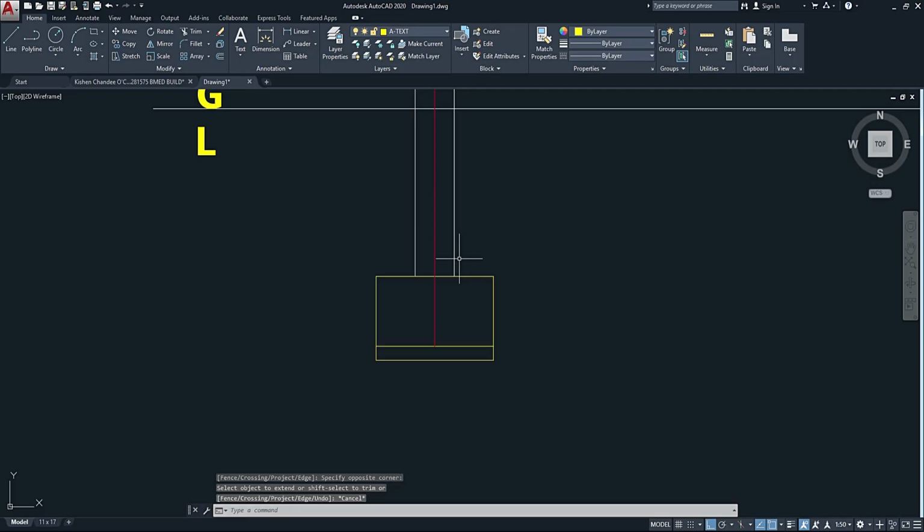and it will stop. So let me offset 0.50 again to this side here like that, and to this side here like that. I'm also going to offset this one here up as well, and I'm going to be filleting the remainder. So I'm going to fillet this to this, and I'm also going to be filleting this to this, and I'll use this line to trim away this portion here and this portion here.